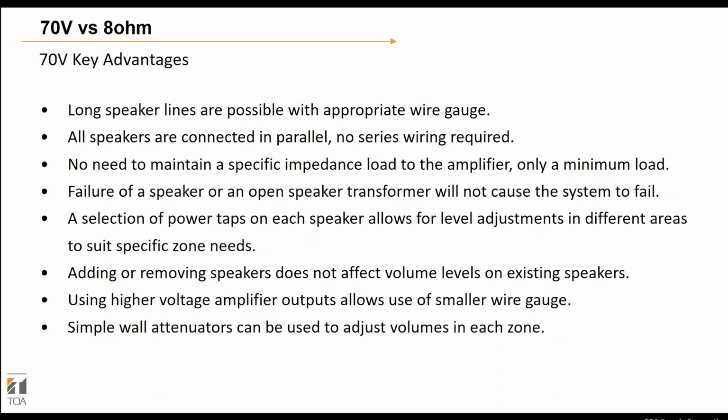You can add or remove speakers very easily, and it doesn't affect the volume levels on existing speakers, which again is different from low impedance, where if you take a speaker off of a low impedance line, it's going to have a huge effect on the rest of the speakers on that line. Whereas in constant voltage, i.e. 70 volt, or high impedance, we don't have that issue.